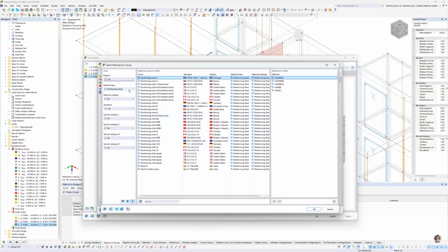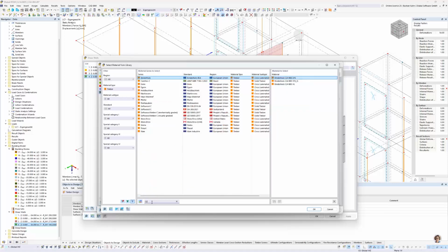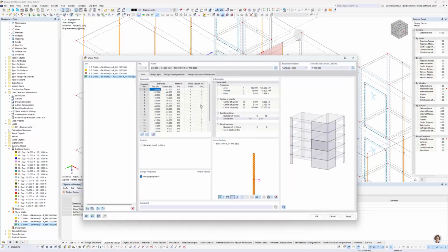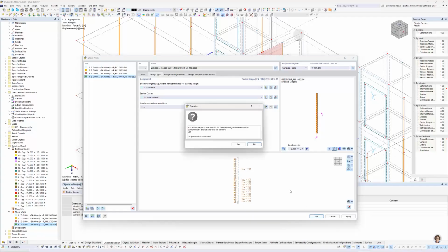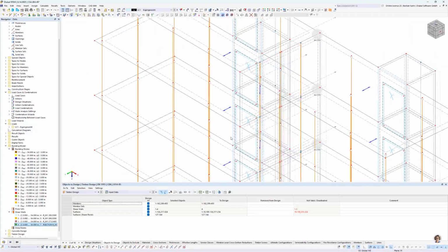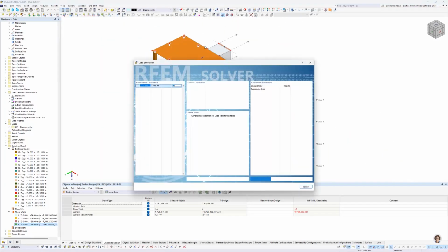I also have to define timber with C24 grade, just as an isotropic material, and press OK. And now I can do a buckling stability analysis together with the stress analysis from the add-on timber design in here. So that's quite a big benefit that the add-on building model can give you, it's not typically software, it's just the add-on.